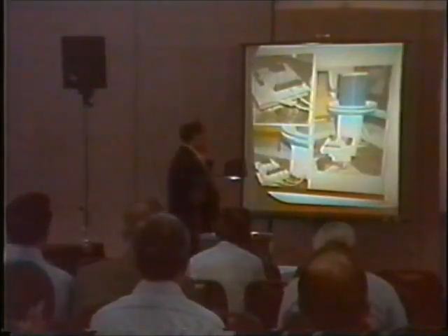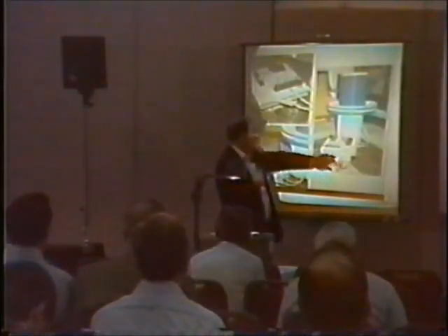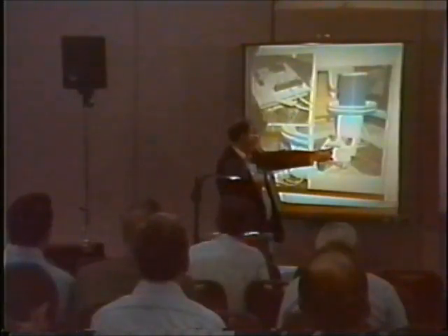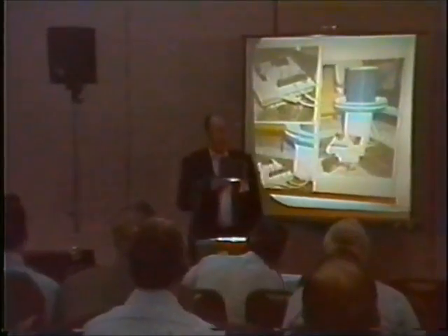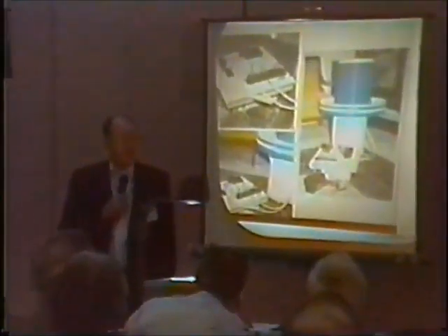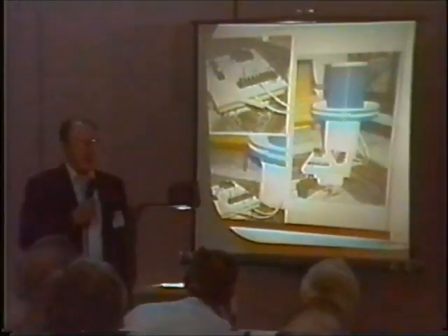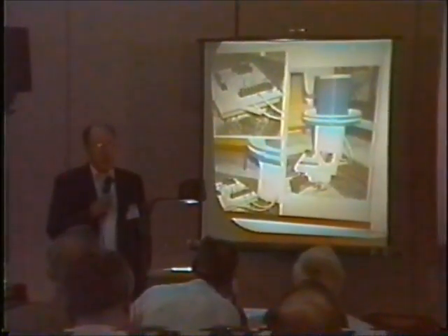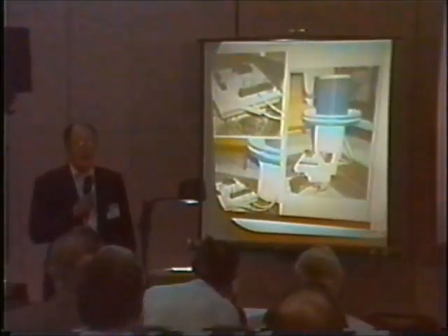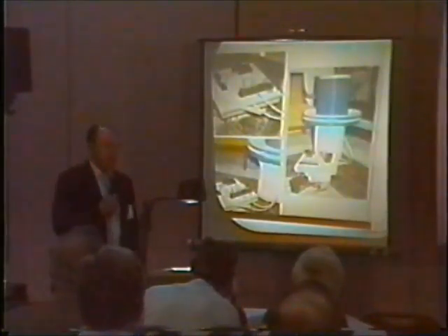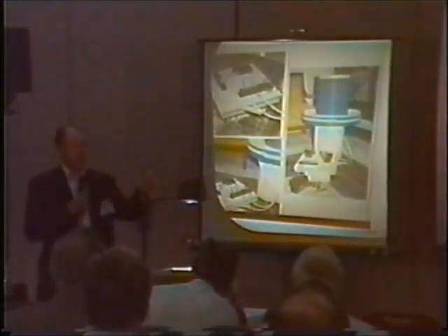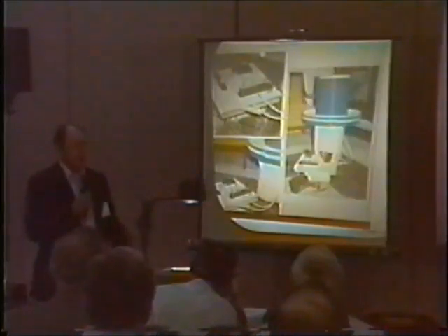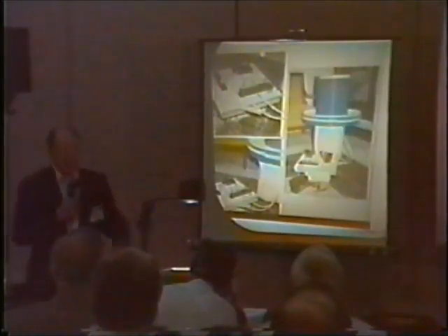And I've built a timing device onto this particular unit. It consists basically of an electrolytic capacitor that's, I think, 4,700 microfarads, and it's not very large. It came from Radio Shack, and I think it was about $2 and something. There's a shunt across the two arms of the capacitor with a resistor on it.